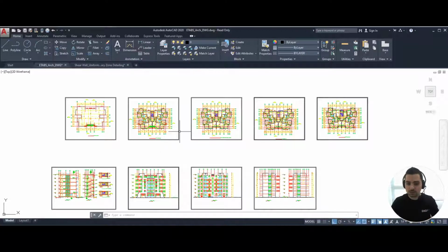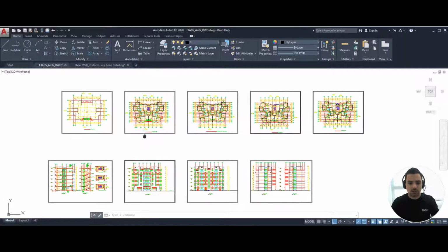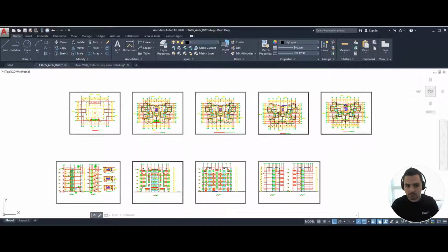Now we are going to start with our last point, which is what steps does a civil engineer go through in order to design a building? The first step is you should determine the type of slab that we are going to use along with its thickness and its structural component, which we learned how to do in our previous chapter, which was CSI SAFE for different types of slabs.